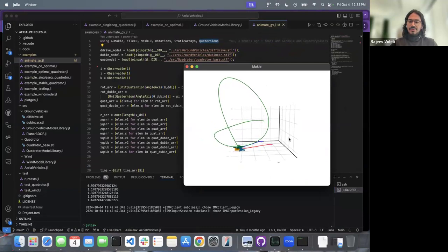And another thing to highlight here is the reason why the quadrotor looks this smooth is the fact that it's a minimum snap polynomial that's generated. And minimum snap means the trajectories are going to be really smooth. The snap is the derivative of jerk, which is the derivative of acceleration. So what the polynomial generation does is it minimizes the second derivative of the acceleration, which makes the approach, the hitting of waypoints, the tracking of the trajectories extremely smooth.